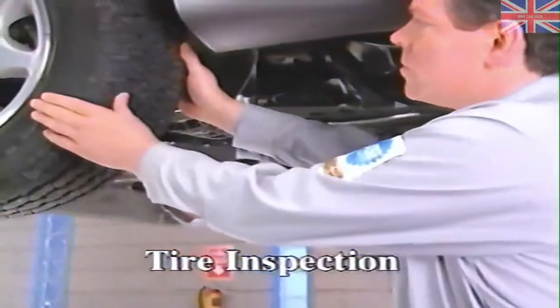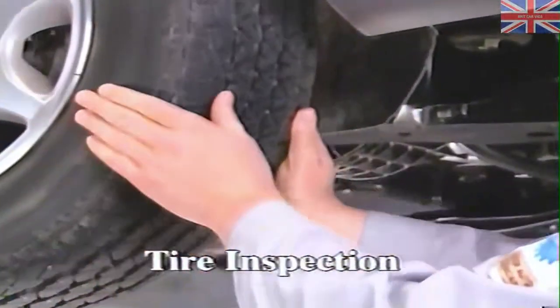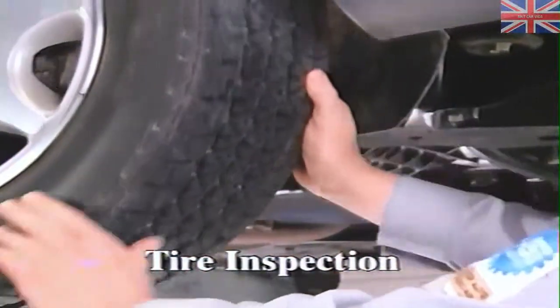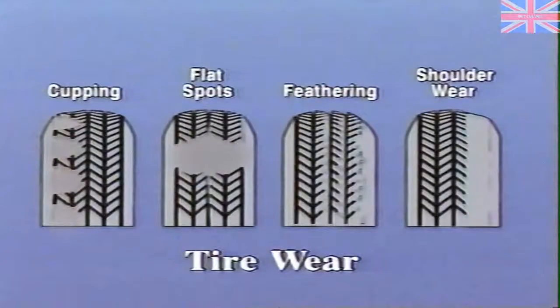A tire inspection should be performed for all noise, vibration, and harshness complaints unless the disturbance only occurs when the vehicle is at a standstill. Check inflation pressure and look for unusual wear, especially cupping, flat spots, feathering, and shoulder wear. These conditions can cause tire growl, howl, slapping noises, and vibrations throughout the vehicle.